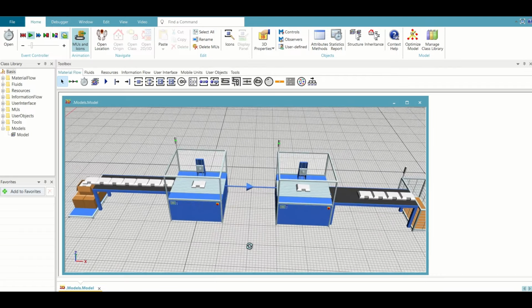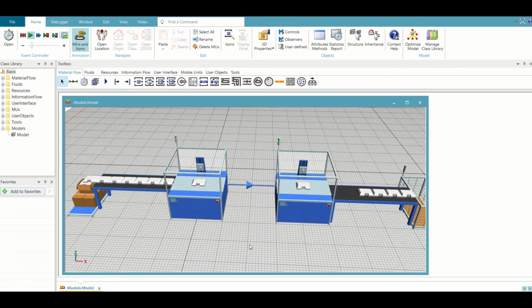Okay, so now, in order to make this station continuously produce, we are going to add a buffer in between. And you can see the impact of station 2, which is now directly happening on station 1, will be suppressed because of the buffer till your buffer capacity gets filled up. Okay, so now let us see how to add a buffer.